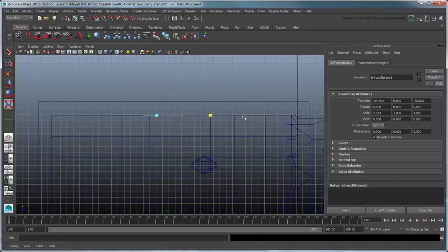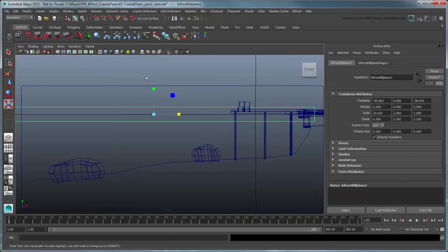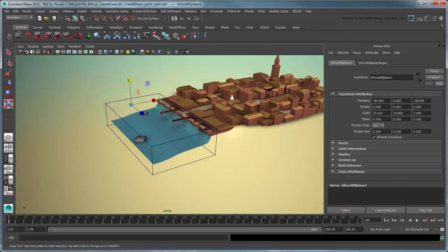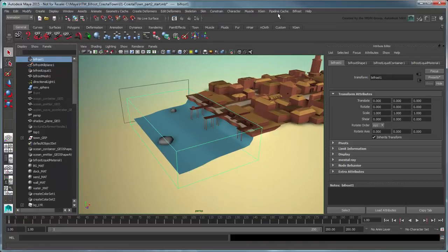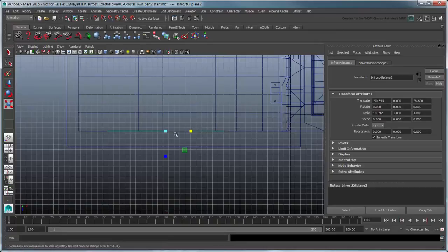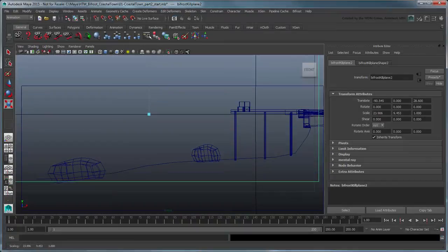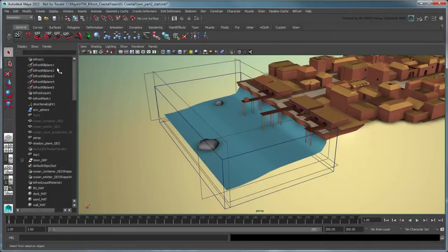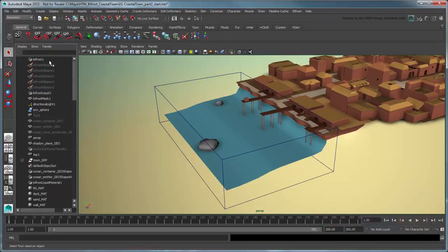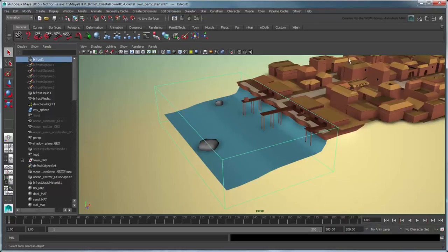You can scale it to better define this border visually, though it's important to note that the plane goes on infinitely. Create 4 additional kill planes around each of the container's remaining sides, and along the bottom as a precaution. Hide these planes once you're done. Now particles are guaranteed to stay in the area you've designated. Re-enable the simulation.